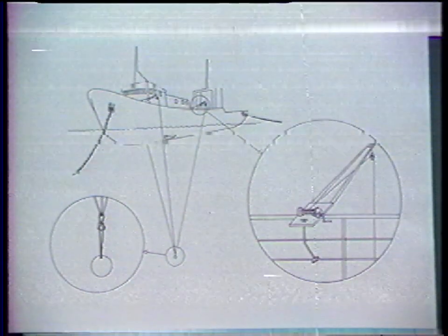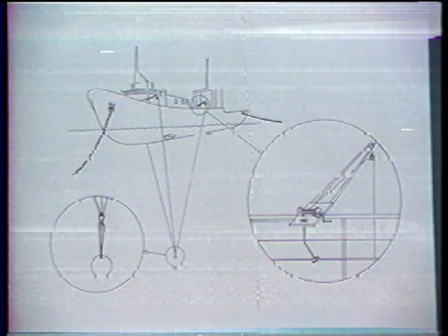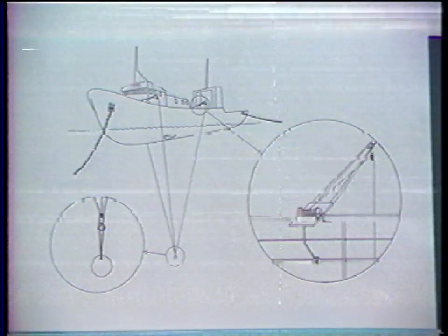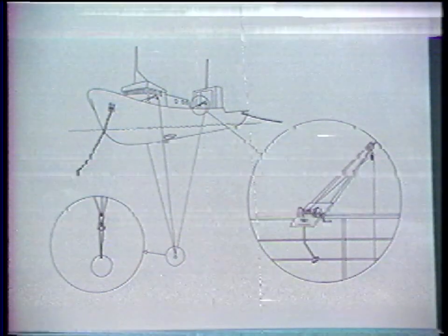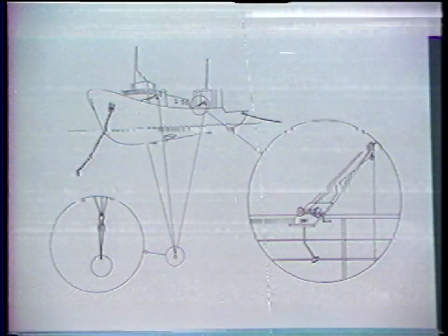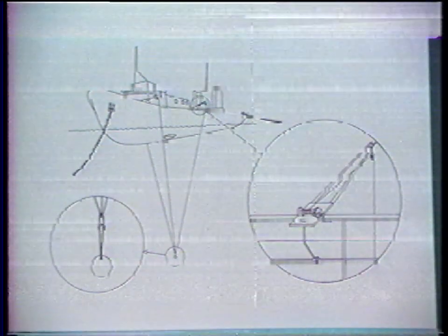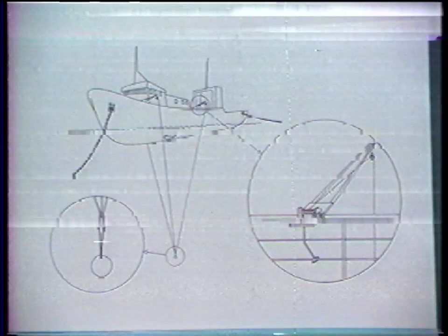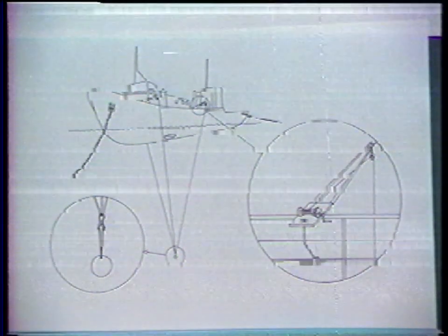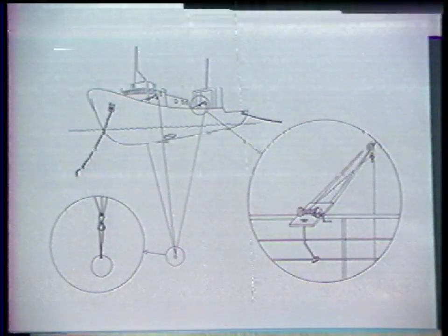Each winch is provided with a long spool of 0.6 millimeter diameter monofilament nylon. This is marked with small lead weights at 5-meter intervals, beginning 10 meters from the loose end. Before beginning the sphere measurements, the lines from the two winches on the same side are drawn beneath the hull to the other winch by means of a line passed under the keel before anchoring.